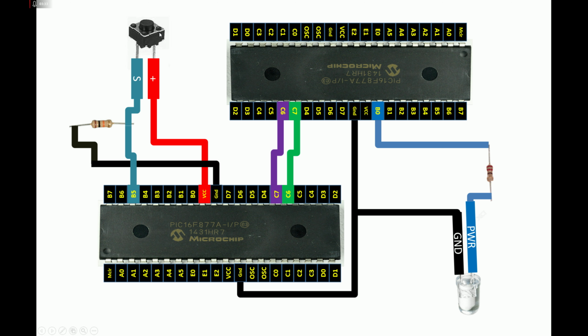Now in this way, our button is connected in a way that whenever it is pressed, a 1 will be sent. A very good indication of knowing whether the button will send a 1 or a 0 is to take a look at the 10K resistor. If one end is at the grounding end, it means that a 1 will be sent. So that's a simple indication. Now guys, we have our LED connected, we have the push button connected.